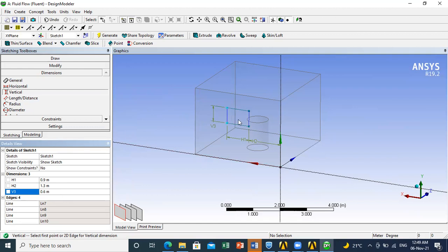And you specify the distance from the floor level, so this is the reference line. If we have a total height of 2.6, and this is 0.6, and you have it 0.2 meters below the ceiling level, then I have 1.8. So this distance should be 1.8.